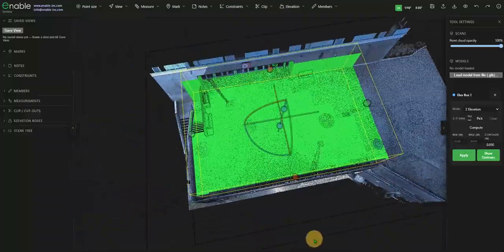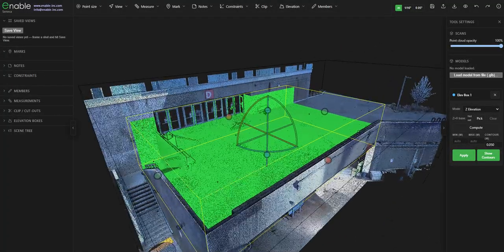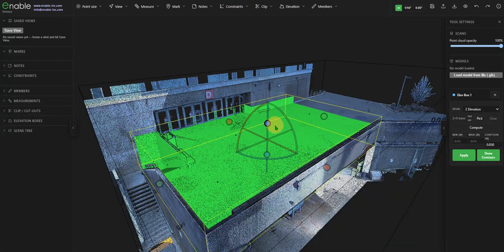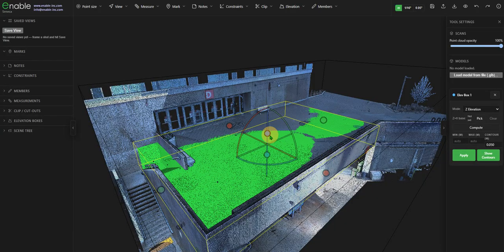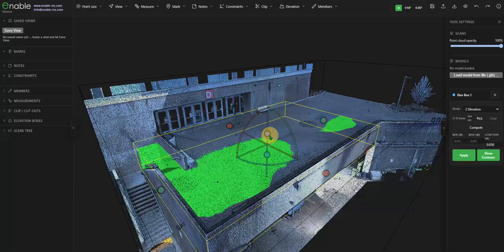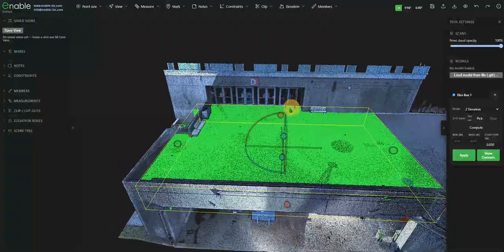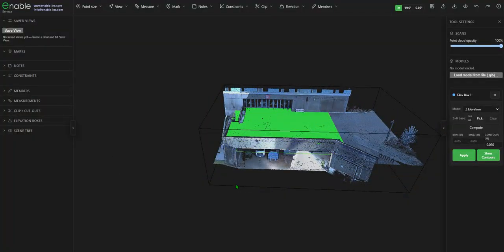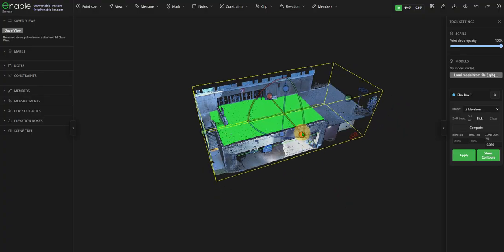And it looks pretty good. With one notable exception, which is that it's too high, but that's okay because I can then bring it down just to the roof deck level. And usually what you're going to want to do is to go through the level of interest till points stop showing and then go back up. This way you can dial in exactly which elevation you want. And you'll do the same for the bottom as well. And this is just to ensure that we're only including the points that we want in our heat map.